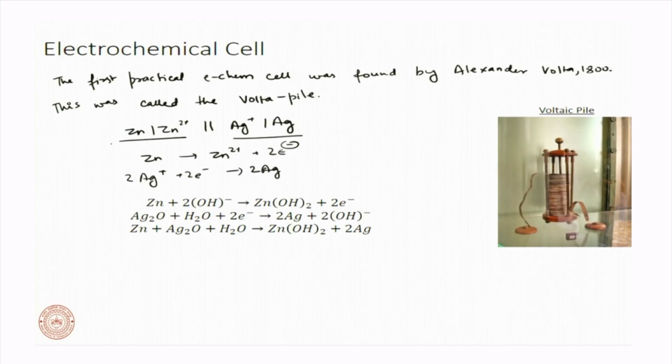And this is the process that is going on in the battery. What is an anion in this case? An anion is the potassium hydroxide, or the KOH. Right. So, in this case, the electrolyte which is providing the anion was KOH, potassium hydroxide, and that is giving you OH minus. This OH minus would travel from silver to zinc through the separator, and the electrons will go through the external circuit.